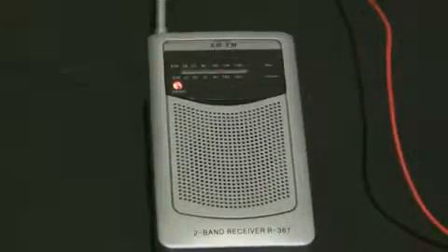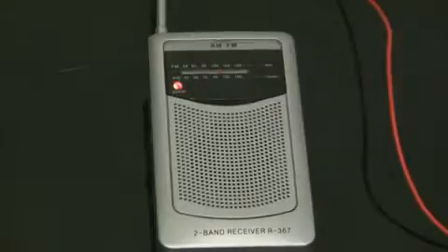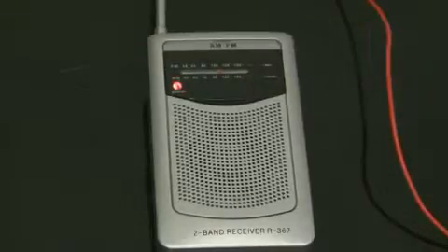Now I'm almost ready to show you a simple telegraph, but first you'll have to bear with me. I live near a broadcasting tower, and there's no way for me to get total radio silence on this cheap little radio. So if you hear a boring news broadcast, just pretend that it's white noise from an empty station. Right now the AM radio spectrum around me seems quietest around 900 kHz. So let's see what happens when I adjust the frequency of my oscillator to around 900 kHz.